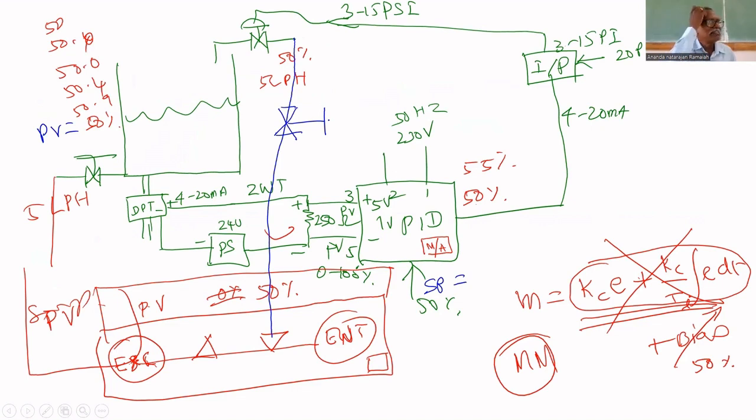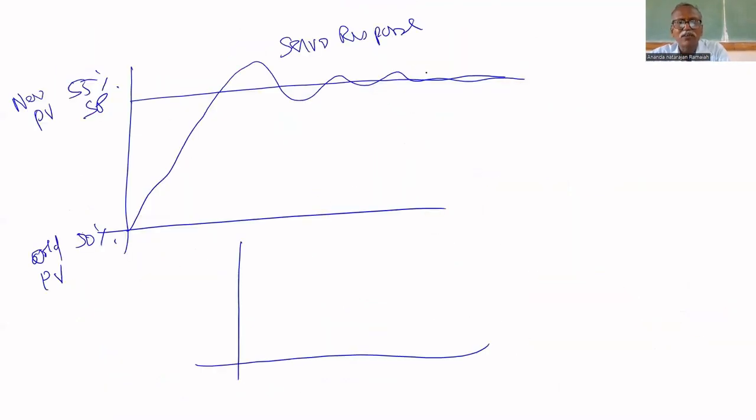What will happen? Flow rate will decrease. Here, when you close this valve, the control valve will open more. So the resistance is adjusted, the flow rate increases again, and it will come back to 50. So you are deliberately closing that valve slightly, not much. If you close it slightly, the level starts decreasing, then it increases and comes to 50. Because of that valve being closed, it comes like this, and again it oscillates and settles. This is called regulatory response.